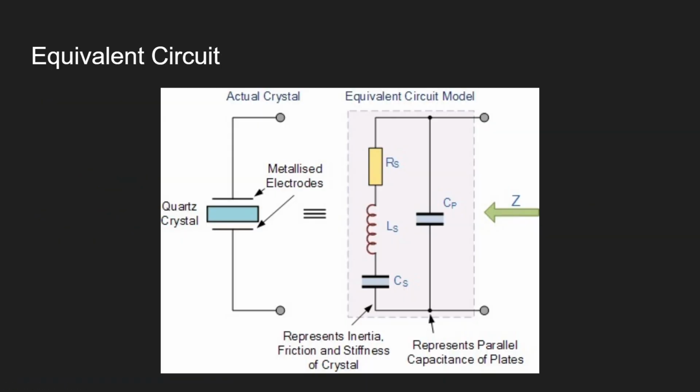Yeah. It is an equivalent circuit. So for a quartz crystal, a quartz oscillator, it can be rewritten as this one, okay? So we have talked about a lot of LC circuits, right? And actually, the quartz itself can be rewritten as an LRC circuit.